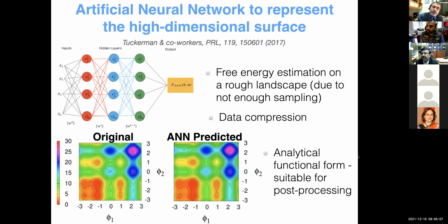But we probably should do just one comparison where we simply run, if you have n umbrella windows, you can do n, let's say 33, independent TAMD runs just from different starting points. I just run them in parallel, and then that would be absolutely equivalent to an umbrella sampling simulation, right? Where you say, okay, there's a certain number of nanoseconds per window, a certain number of nanoseconds per trajectory, and then do that comparison and just see how they stack up.